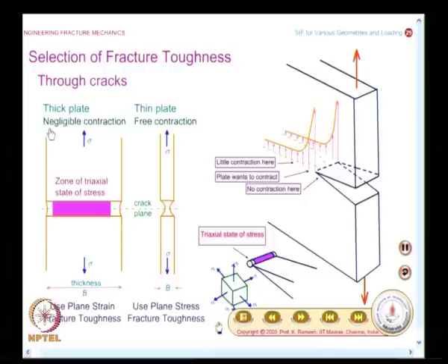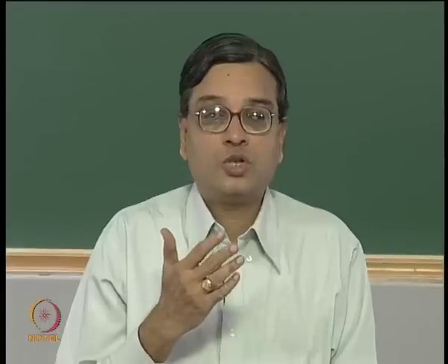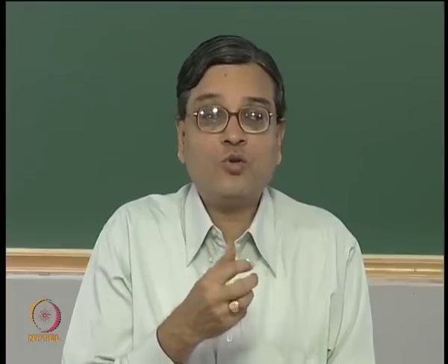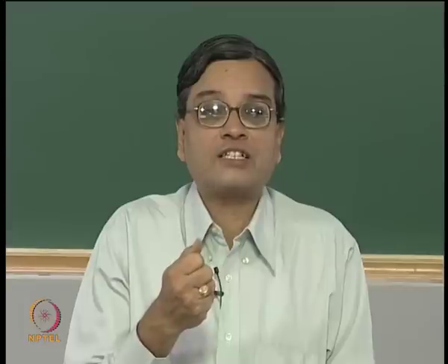And you find there is negligible contraction in the case of a thick plate. So, in such problems, from fracture instability point of view, what will you have to do? You will have to calculate the stress intensity factor when you have a crack in a thick plate.